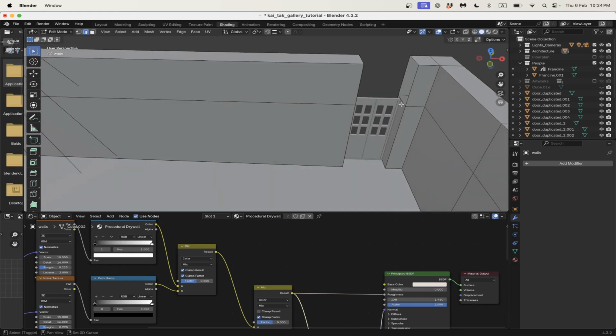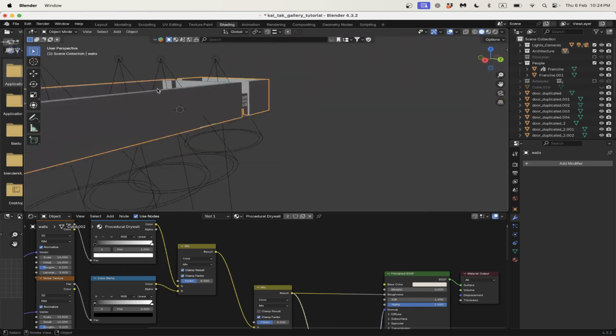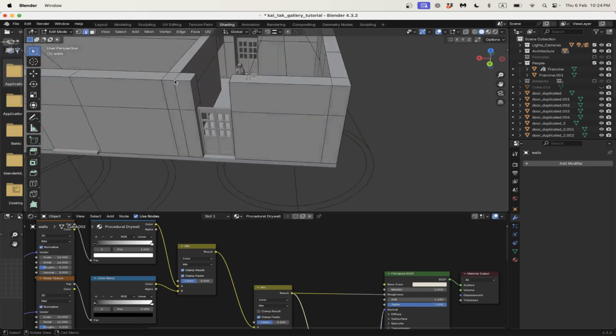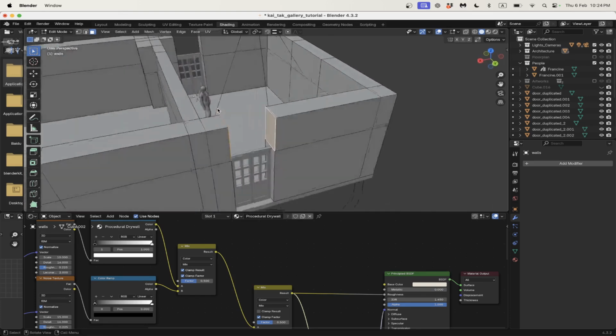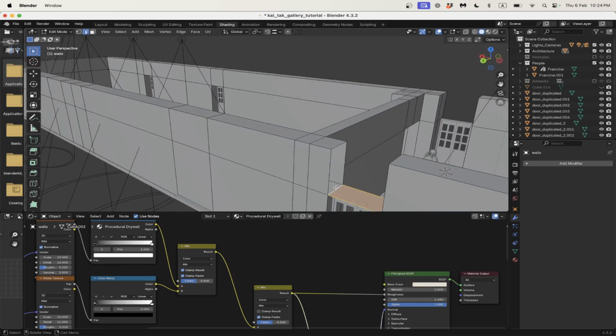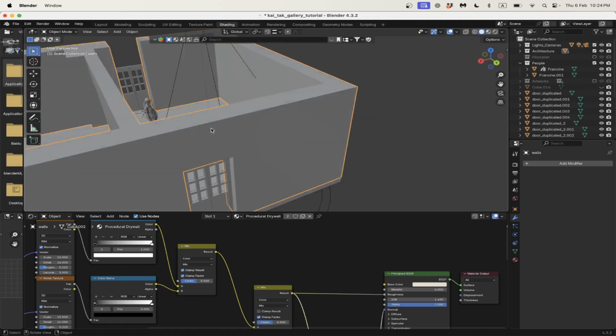Here I am again, just deleting these faces, selecting my edges, Shift to select multiple edges, and completing the geometry around the doors. Okay, let's just get to this final door here. Oh, no, there's two more, sorry. So face mode by pressing 3, delete these two faces, F for fill, good, and the last one over here.